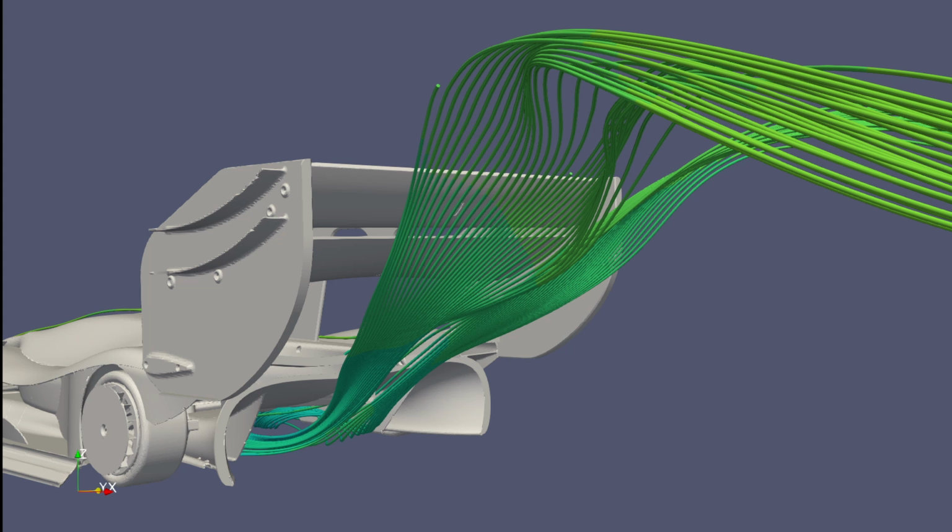The rear wing and gurney at the back of the body actually help to create a massive upward flow at the back of the diffuser, which draws the air through the underfloor. I think of it like a giant vacuum cleaner sitting right there behind the diffuser. I spent a tremendous amount of time optimizing the placement of the rear wing, and the lower and further back the rear wing was, the more effective it was at helping the diffuser.